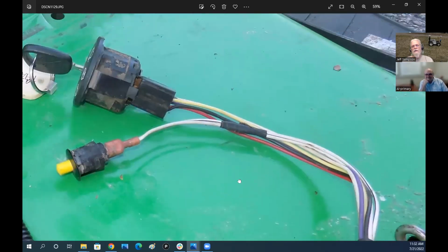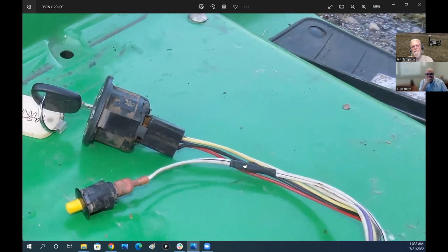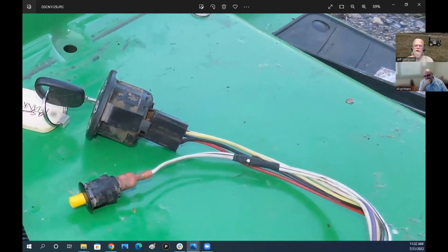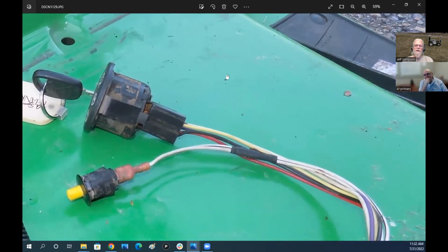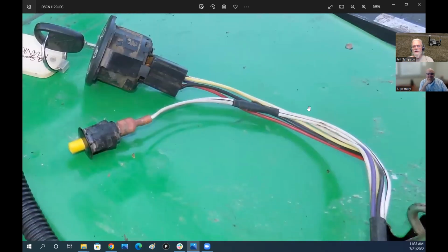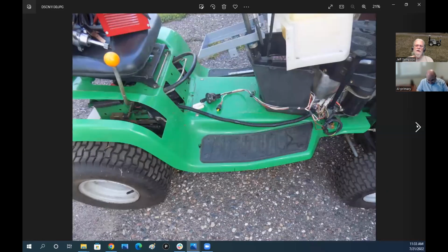And I don't recall if, well, we're not going to be able to tell from these pictures because everything's too dirty and we can't see what's going on. But I think that looks like a spot weld that's not marked. So probably when I took the solvent, it took off my marks that I'd put on. But that looks like a spot weld right there. That looks like one right there. And as I say, I don't see the ones out in the middle, but I'm sure they're there. So anyway, I figured that's how I can get my references, to use those spot welds.